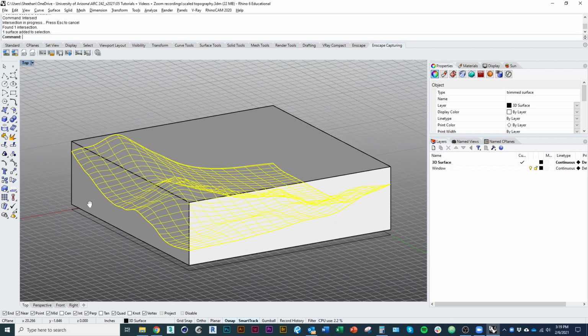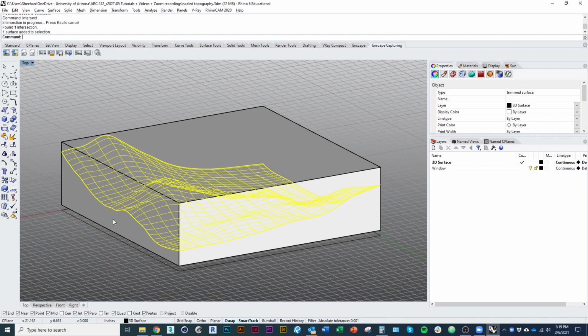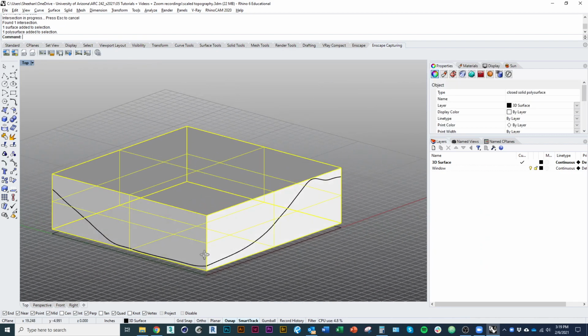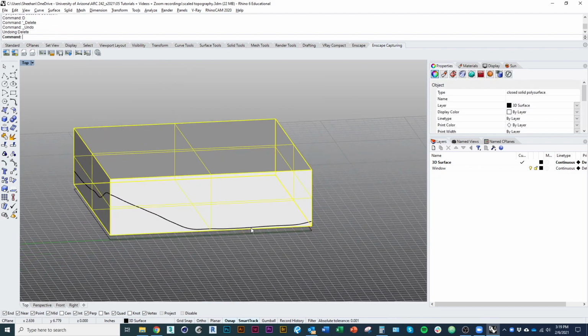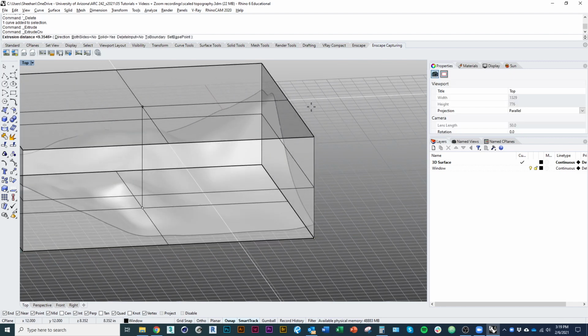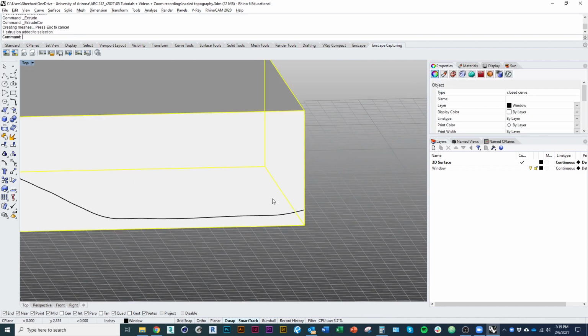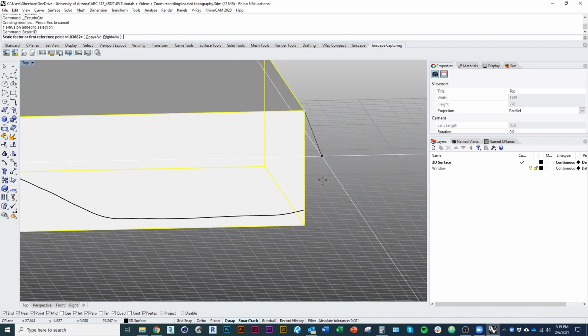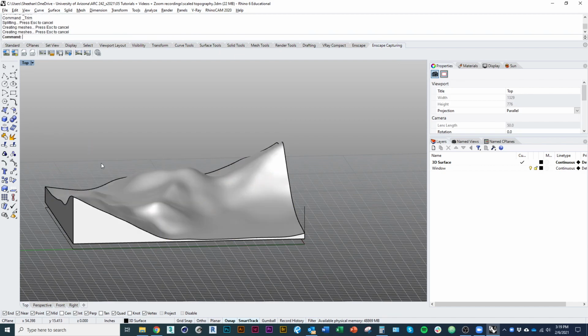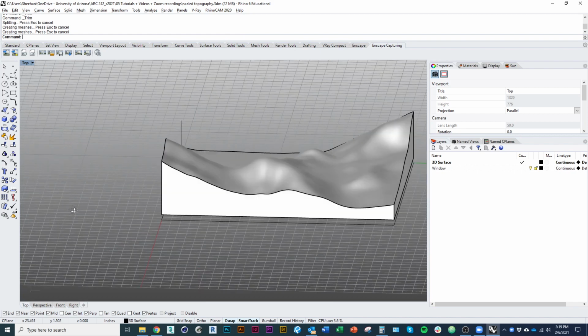It could just be kind of a weird tolerance issue when I trimmed the surface originally. There's a couple things we can do to fix this. So I still have my curve. Oops, I don't have my curve. I'm going to go back a couple steps so I have my curve there. And I'm going to try and trim it instead by extruding this window. And then scaling it to the bottom of my curve there. See if that works. So I'll select my surface, type in trim.